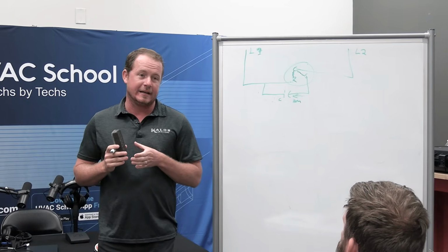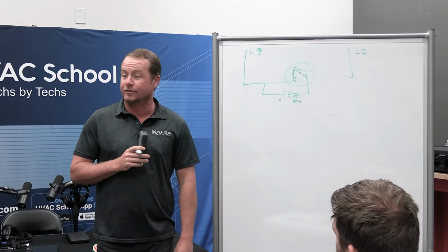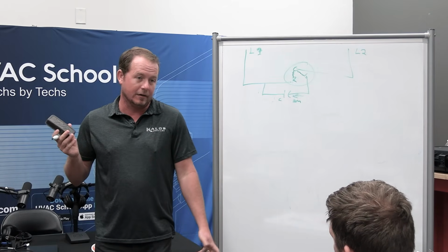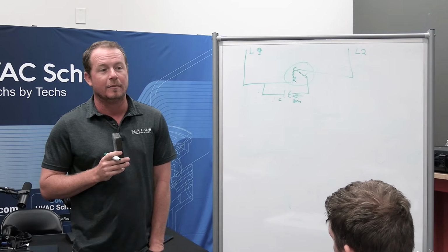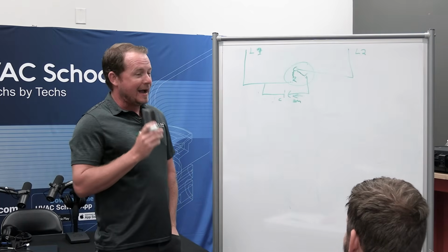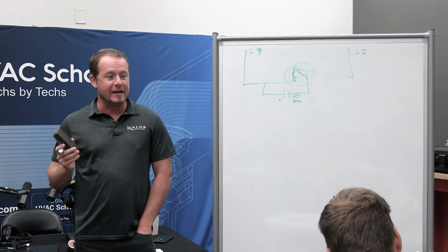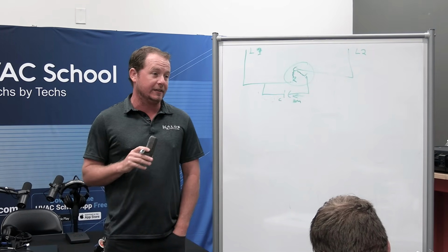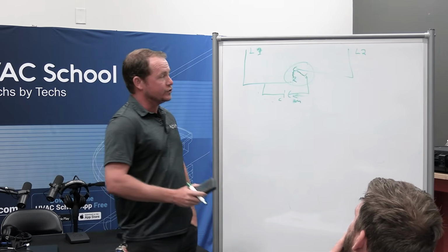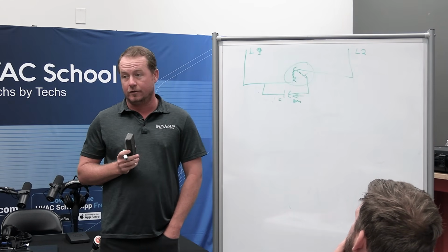I have a lot of people say capacitors never go weak. They're either good or bad. Is that true? No. That's bunkum. I don't know why people say that. And maybe it was 20 years ago, back when people used to use the word bunkum. Capacitors do get weak. And when a capacitor gets weak, it results in that motor not starting as quickly as it should, which results in stress on our run winding, because our run winding is staying hotter longer than it should.